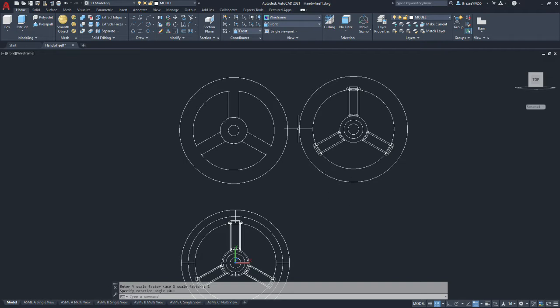It's more busy. So if we're going to go with this display, we're going to want to connect these webs here because there is an edge there. It's just not picking up on a hard square edge. So after we do our explode, you would connect those arcs in there to give it an edge, to reference that there's a change in surface there.